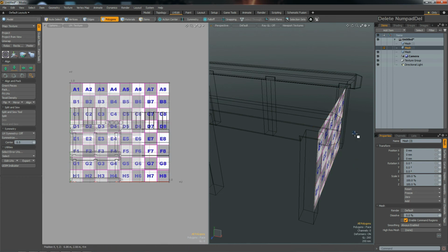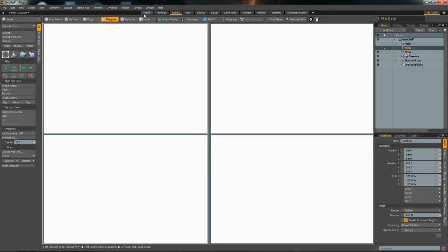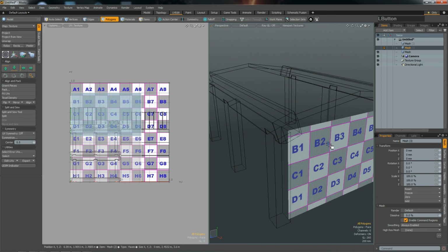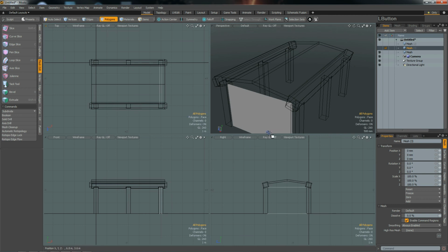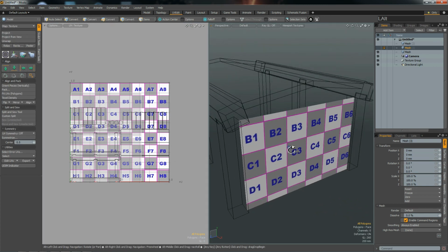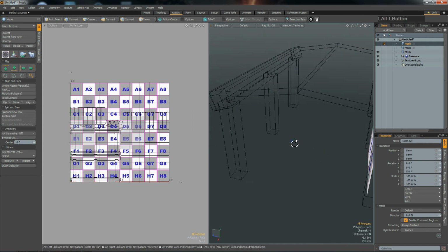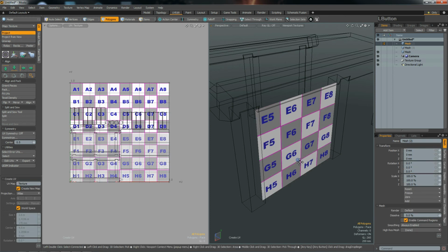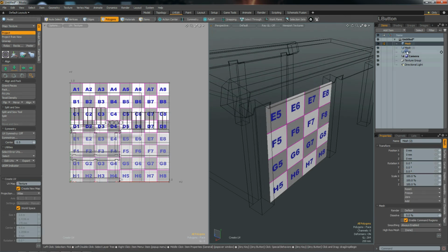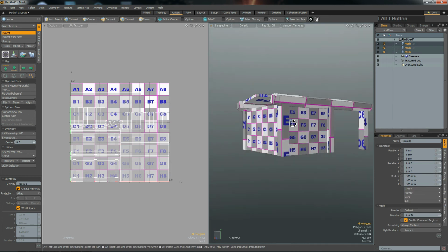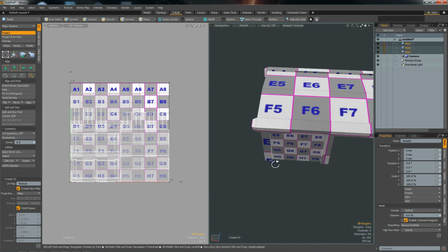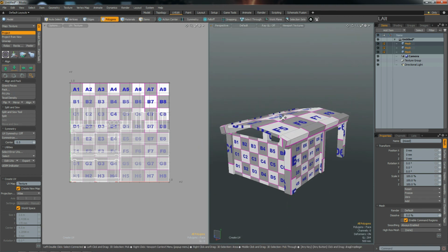And if I delete that here, I can work just here in this viewport as in the modeling viewport. As I said, it's not a different editing mode or something, it's just a different way of laying out things. I could also add here a UV layout in addition to that if I wanted to. So this really just splits the viewport into different layout setups. And also we're gonna flip this. So we end up with a UV map that looks like this, and that's quite okay.